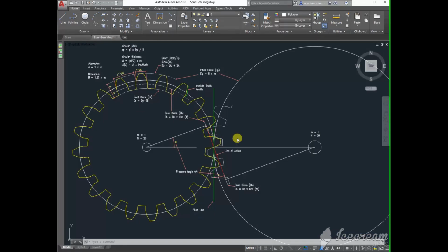As mentioned before, the y component of the force will create torque on the driven gear, thus rotating it accordingly. The x component, Fx, is insignificant in the system and will be transformed into heat and noise as a result of friction. As we increase the pressure angle, the y component decreases while the x component increases, resulting in less torque and more friction. So can we say that it's better to minimize the pressure angle?